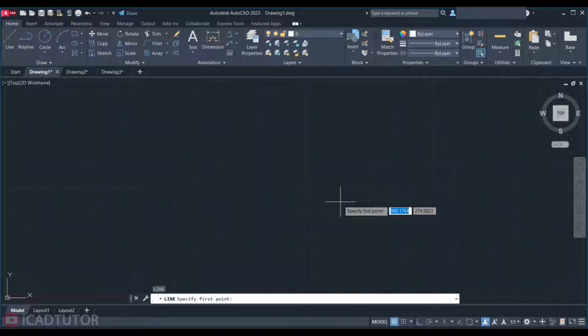Activated just as easily. You may want to ask me, how do I know it is activated? First, if you look at the command line, you will see that it is activated. The tool's name is bold and it means that you can use it. Secondly, if you look at the drawing area next to the mouse cursor, you can see the gray and blue boxes. It means that the dynamic input is enabled.